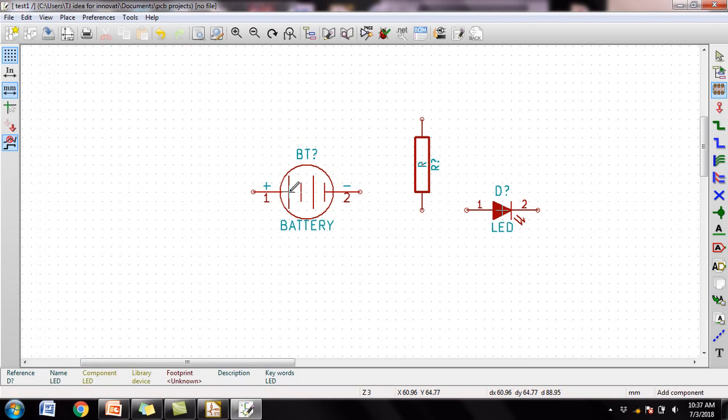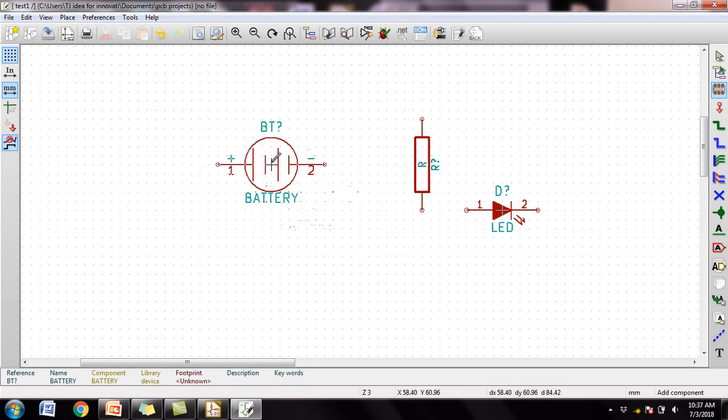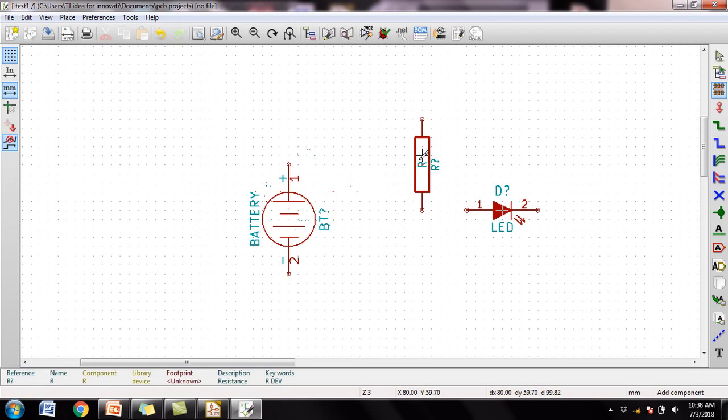I became very familiar by practicing, a lot of practice. So for movements, we place the cursor over the component which you want to move and press M. The component will stick onto the cursor, and you can start placing it anywhere you want. And if you want to rotate it, just use R, so that you can rotate the component and place it.